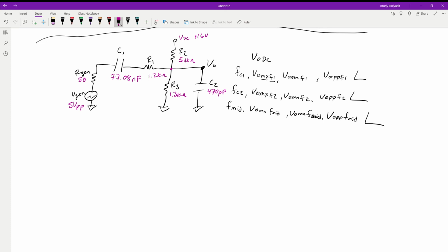So the only place that we have our DC current is simply our DC supply VDC, R2, and R3, with this being our V out across R3. So when we have just two resistors, it's a simplistic circuit. It's just a series resistive circuit. We can use voltage divider. There's no phase angles, nothing else.